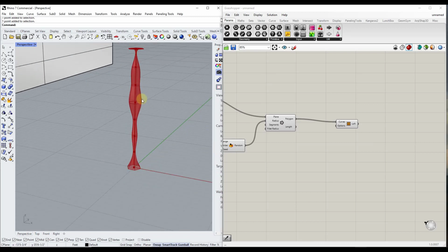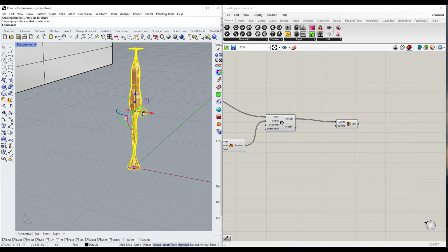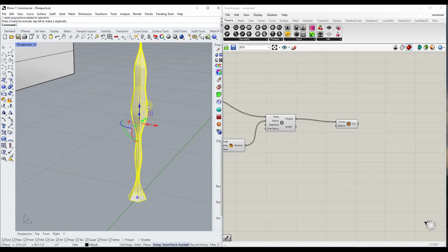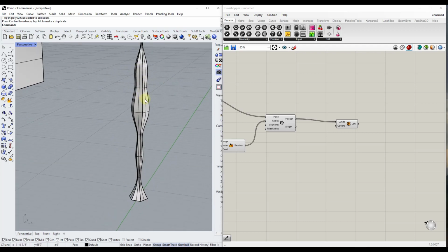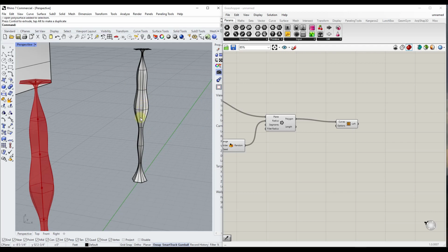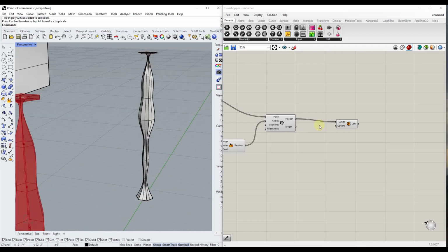Well, then we could take this shape, right click on it, and we could bake it like this, and we'll just call this organic shape and hit OK. What that does is actually generate the shape in 3D inside of Rhino. So you probably wouldn't create a shape like this, but you might use this to create some really interesting walkways or other things like that procedurally. So once you understand the way that these come together so that you can use them in order to generate different shapes, this gets really powerful.